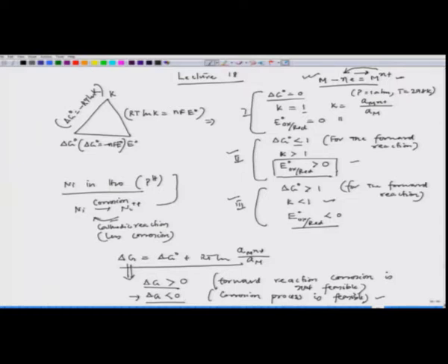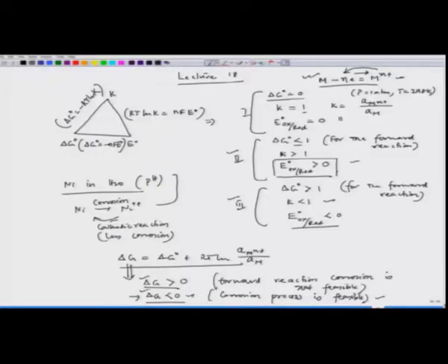See, in order to know this, we have to have a numerical problem, and then we would be really clear that yes, if we have this condition, that means this is the pH level, this is the temperature, this is the pressure level, then we can decide whether a particular metal would corrode in that particular solution. And when we talk about corrosion in that particular solution, that means the corrosion process becomes spontaneous. And when we talk about spontaneity, we have to consider free energy change, and we have to say this condition is met. Now, in order to do that, we will take up a problem.